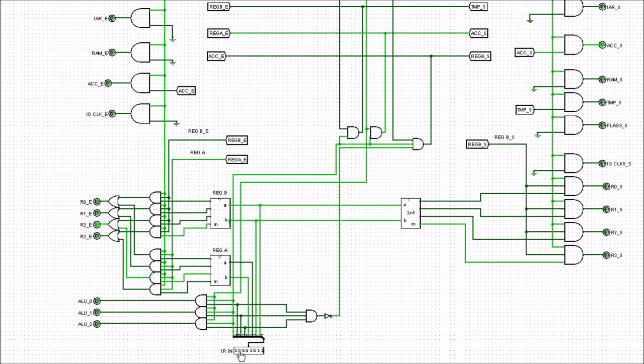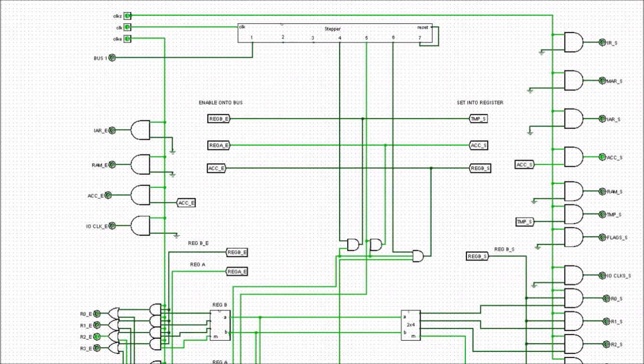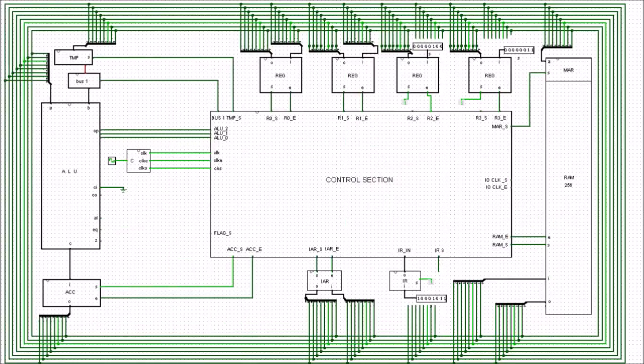So it means that the value here, the 000, will pass straight through these AND gates. Okay, so if I change these to any particular value, these 3 bits, they'll now appear at this output here. So we also have our opcode all set up. So now we're ready to go on to our final part here, which is part 6. So we'll go up to the top level and we'll pulse it again until our clock enable goes high.